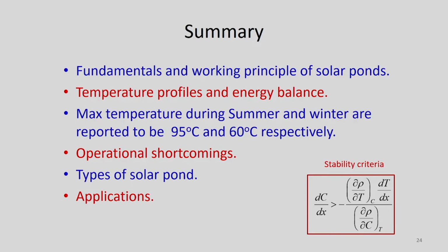On top of it, we have studied the stability criteria, how to calculate the minimum concentration to operate a salt gradient solar pond.